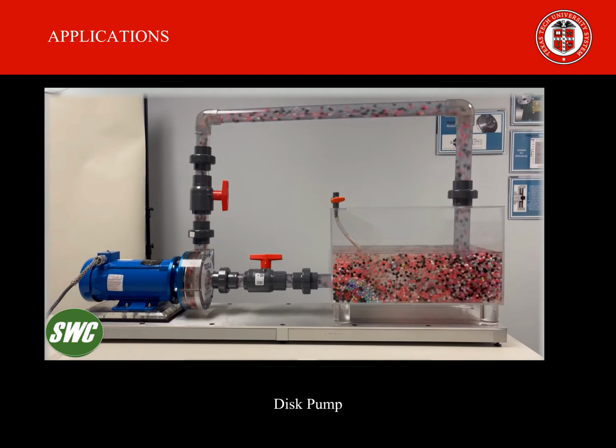Next, consider the applications solely as a pump. Southwestern Controls demonstrates their collaboration with Tesla disc pumps to move large volumes of heterogeneous solutions. Oil drilling requires mud to be displaced out of active wells. Normally, this poses challenges as used mud comes back with rocks or gas pockets. Sending either of these contaminants through a conventional steady-state pump causes blade damage via impact or cavitation, respectively.